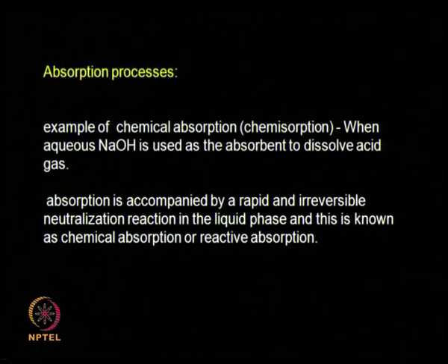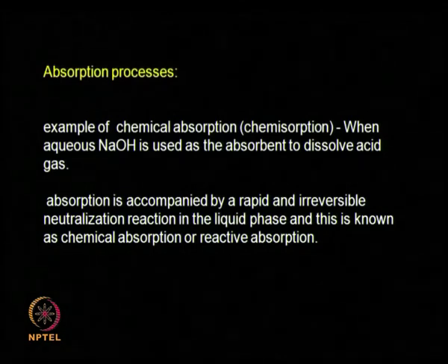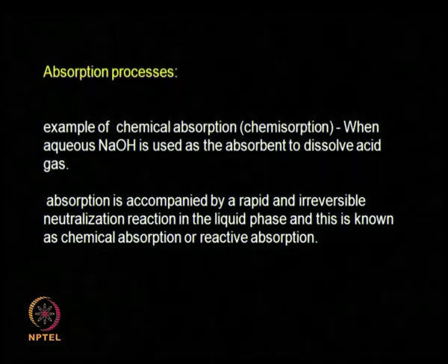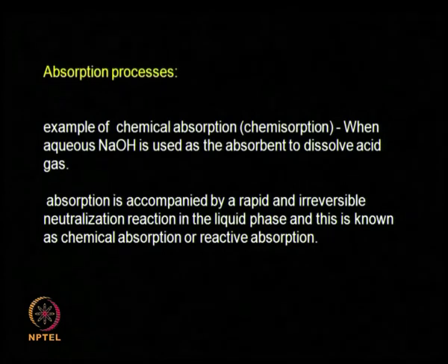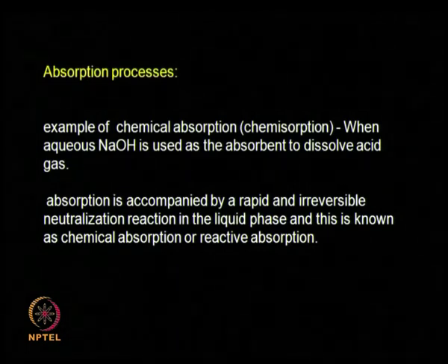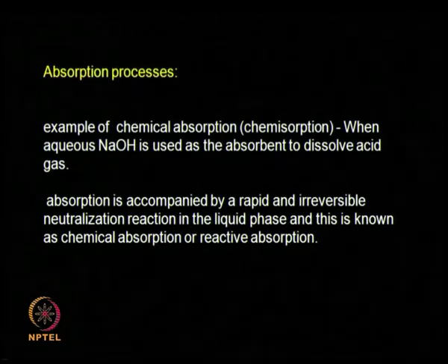Okay. What is a chemical absorption? For example, if I am using sodium hydroxide to capture certain acidic vapor or carbon dioxide, then what happens? The carbon dioxide not only dissolves in sodium hydroxide, but it also reacts and sodium bicarbonate is formed. That is a chemical absorption. Or if I have a dilute acid vapor, they dissolve in sodium hydroxide, they also react.